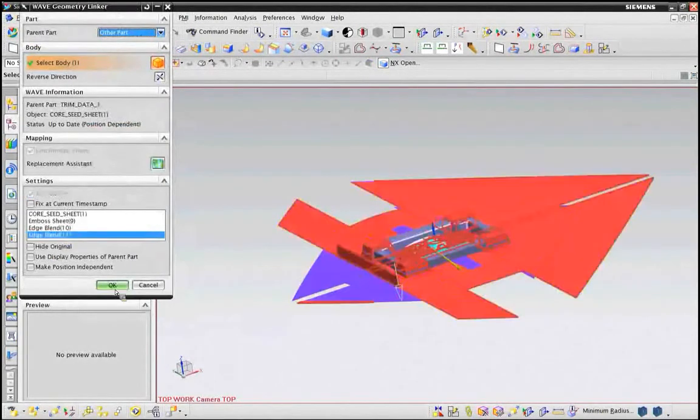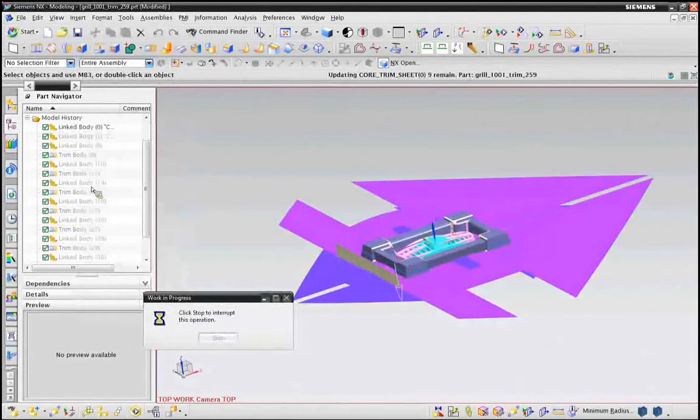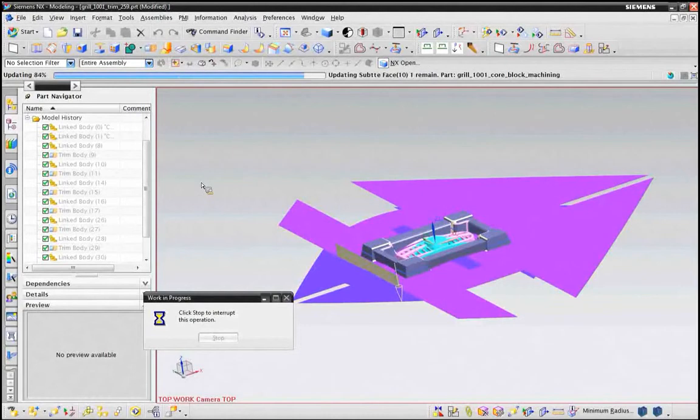And typically in any engineering process, I'd probably have to develop that parting line, spend a little time developing that parting line. But for the purposes of this presentation, I'd already done that work. So all I have to do really is go back in the history of the parting line and reselect the new faces that I want to use as the parting line. And NX has that power and capability.